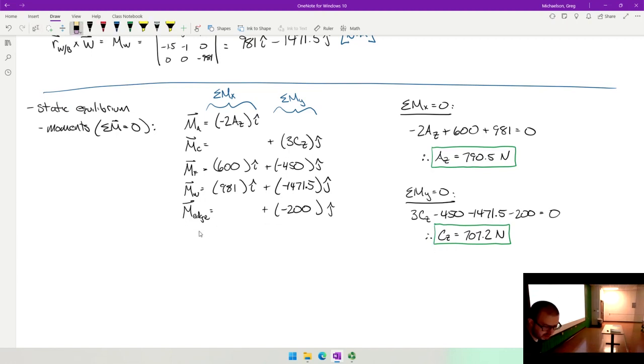You can get rid of that line because I don't think that really matters at that point. If we now consider summing forces, remember this is an equilibrium problem, so we know that the sum of those forces must be 0. Put a vector over that 0. So what forces do we have in this problem? Well, we've got the reactions A, B, and C. We've got the force vector and the weight. Remember, the edge moment is a moment. It's not a force.